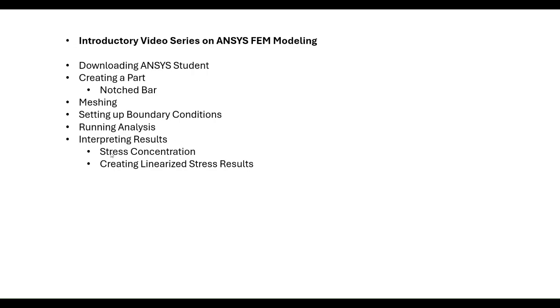So we'll calculate the stress concentration from the FEA model and compare it to hand calculations. And I'll also show you how to set up a linearized stress result that you can do with the model so that you can extract stress concentrations directly from the model, which is a typical method used in industry.